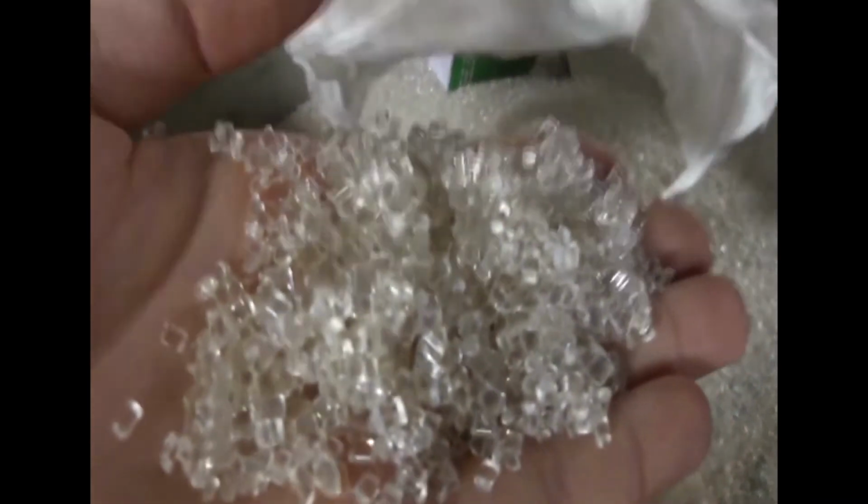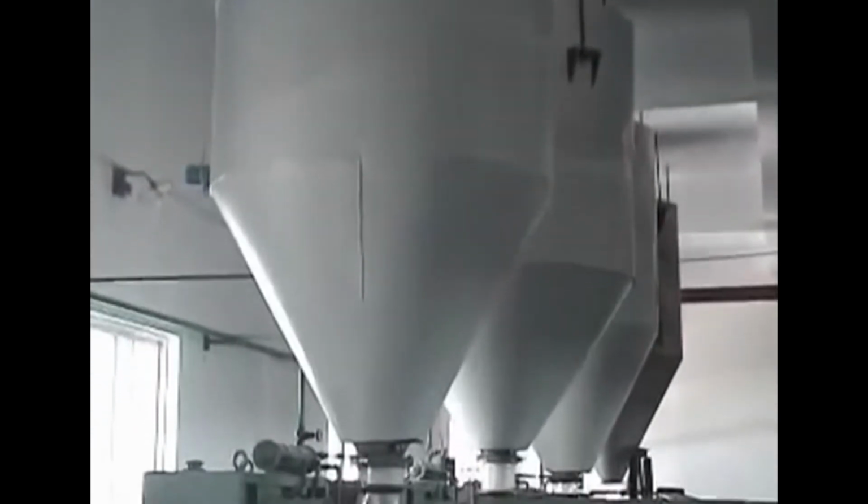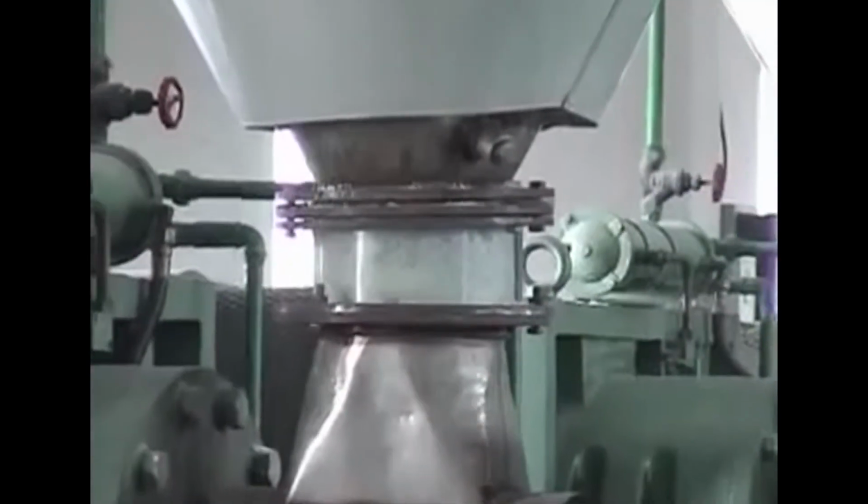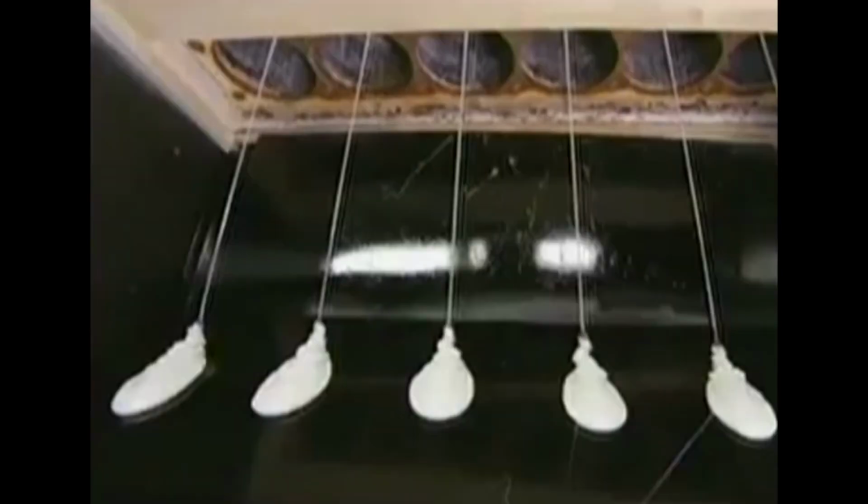In this, first polymer chips come from the chemical factory, and they are placed in a hopper. Chips from different machines are brought in and put through the hopper, where they get mixed to get a uniform polymer, and then they are made to fall on a hot grid. When it falls on the hot grid, it melts, and the molten solution is collected and then filtered in order to remove any suspended impurities which will interfere with the holes of the spinneret. They may block the holes of the spinneret and stop the formation of the filament.